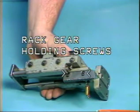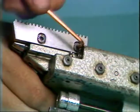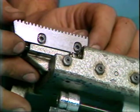These are the rack gear holding screws. The screws hold the rack gear in position. Both screws are loosened to adjust the position of the rack gear. The gear is adjusted to mesh firmly, but not tight, to the half-circle gear. This will ensure that the 2 gears do not bind or have excessive play during operation.